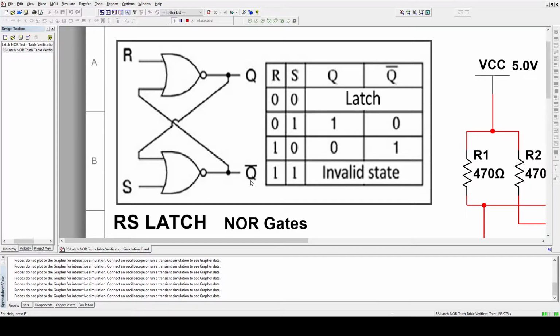And whatever the Q is, in digital electronics it would be 1 or 0, logic 1 or logic 0, and this not Q is just the opposite. So if this one is 1, this is going to be 0. If this is 1, that is going to be 0. So they will never be both the same, because we only had that one stick and we could only swivel this one way or the other. So if it's one way, it's not there, and if it's there, it's not here.